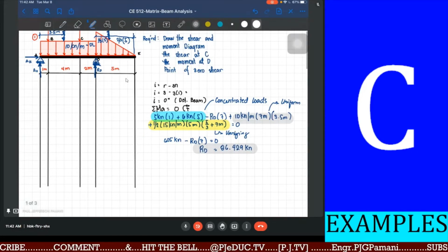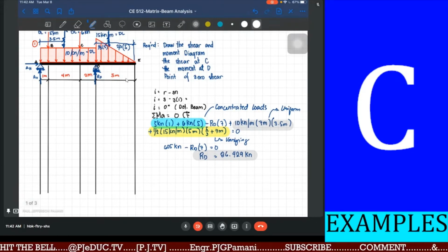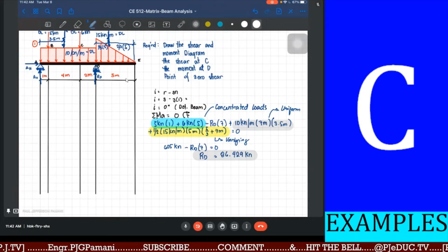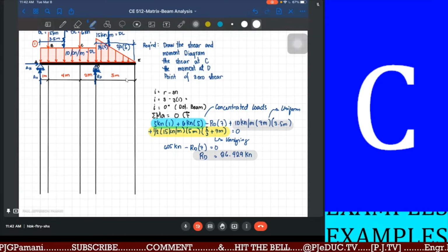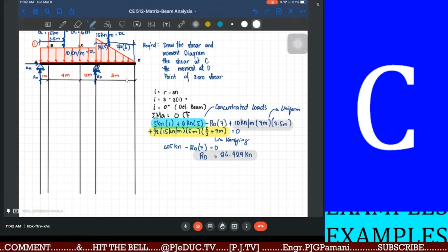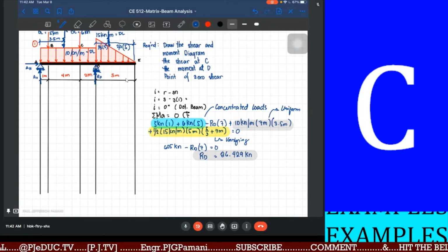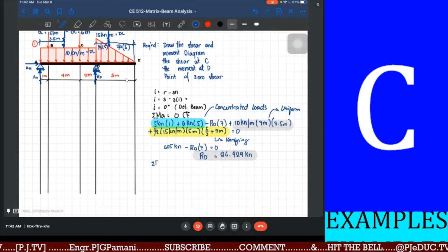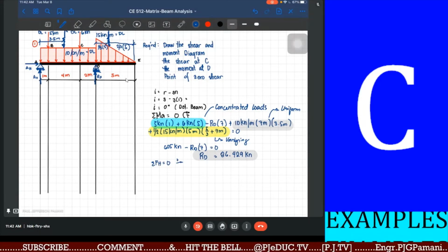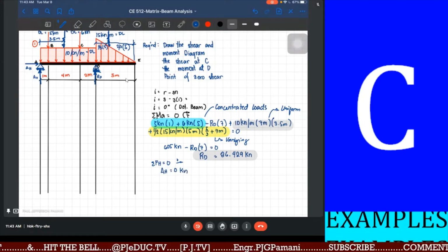So, anong gagawin naman natin dun sa reaction at the hinge support? Para mas mabilis tayo, do we have an actual force applied on our beam? Do we have an actual force? Horizontal force. So we don't have horizontal force. So by summation of forces horizontal, we can then immediately solve. Going to the right, positive. AH is now equal to 0 kilonewton.